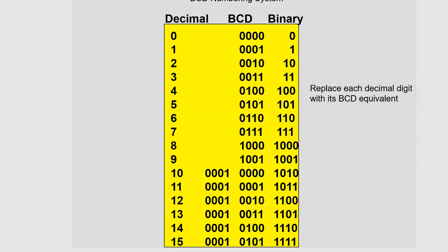But in BCD, you don't write it this way. You write it like this. I want to represent the 1 using 4 bits, and I want to represent the 2 using 4 bits. And that way, let's say I have a 7-segment display that counts from 0 to 99. So I would need 2 7-segment displays, because each 7-segment display can only display the symbols 0 through 9.